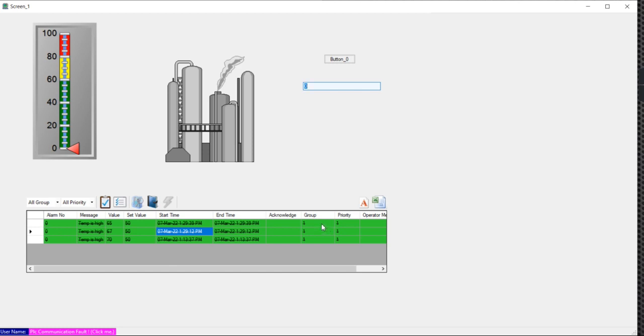So it's struck out then. Normally, you would see an alarm, and it will stay there until the value goes below the alarm level, right? And you have a log of all these alarms. If I enter 35, no worries, nothing wrong, right? But as soon as I go above 50, it's going to give me an alarm and record that for later, and it's reset as well.